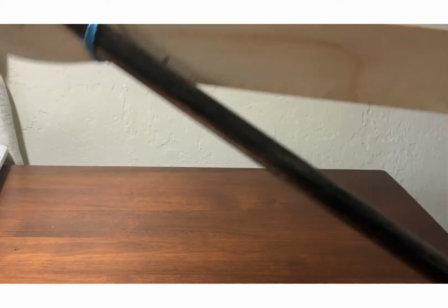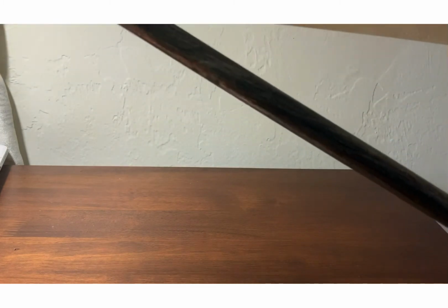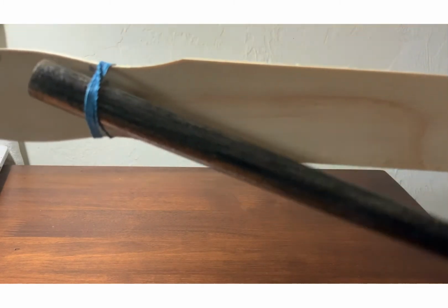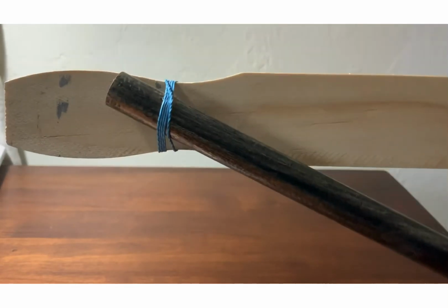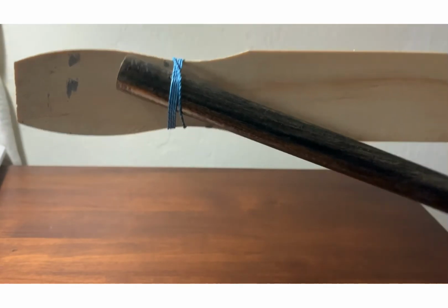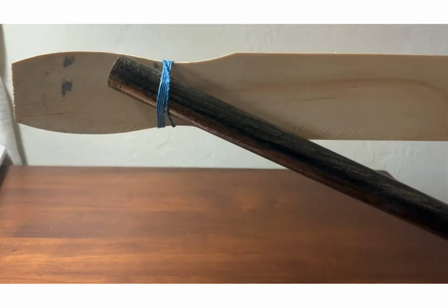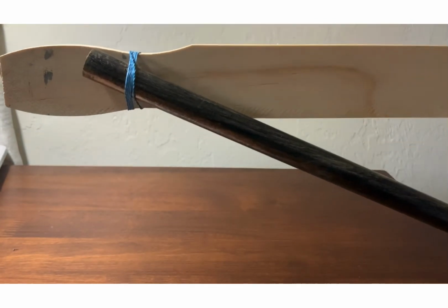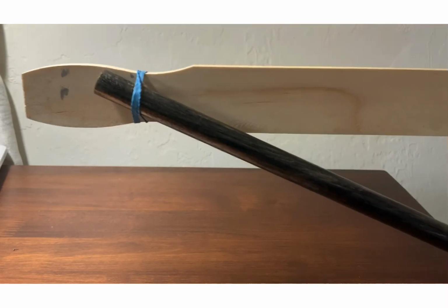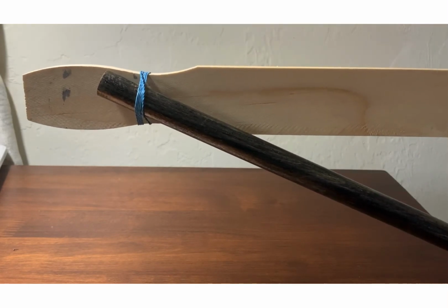If we have a brown bar here, and that support, as you can see, cannot move up or down, but I can rotate, that can be considered a pin. So two unknowns with one body in 2D, of course you can solve for that. Now what if we introduce more unknowns?